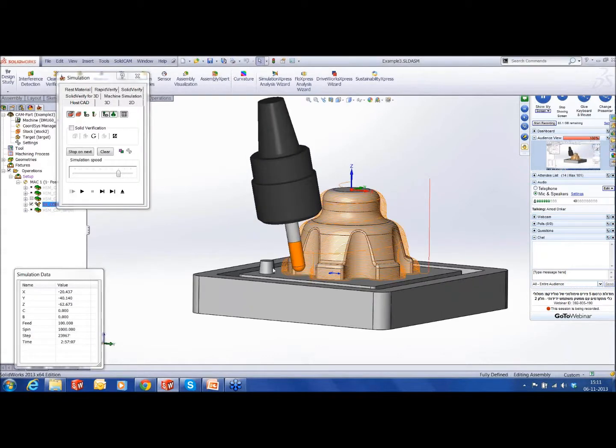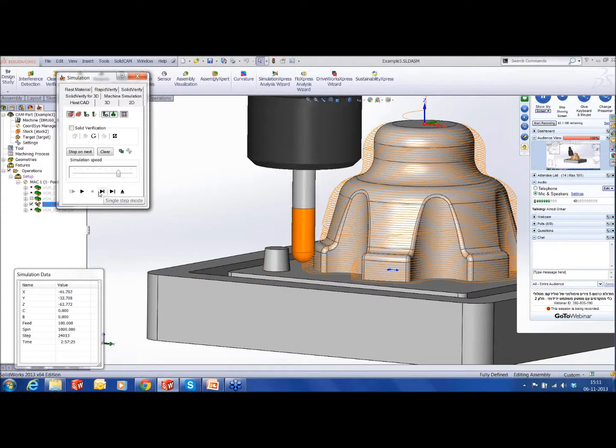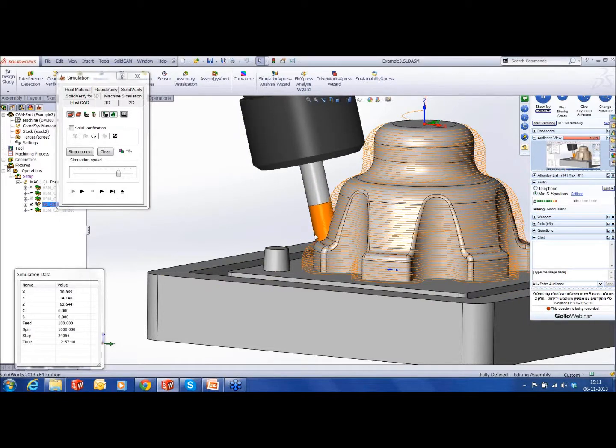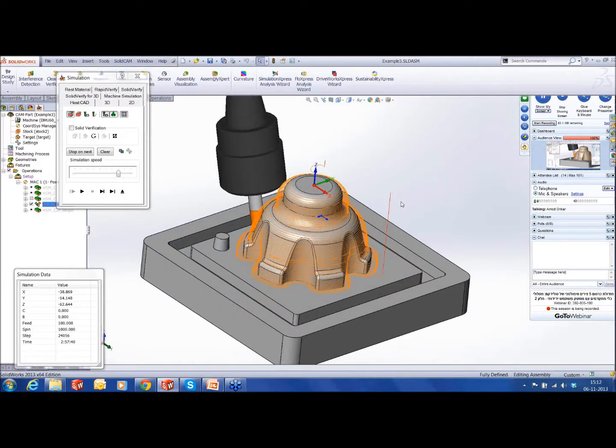Let's see what happens out here. It's again trying to be straight because there's another fellow coming up here. It can't tilt too much. And again, as it finishes, it's going to go into tilting again. So you can see that it was pretty easy. Just take the tool path, set your conversion to 3 to 5-axis conversion, calculate. You can use short tools, cut deeper into the part without compromising on parameters or surface quality, or for that matter even gouges. Your toolpath is checked for gouges 100%.